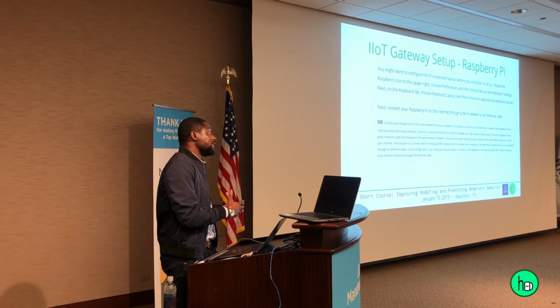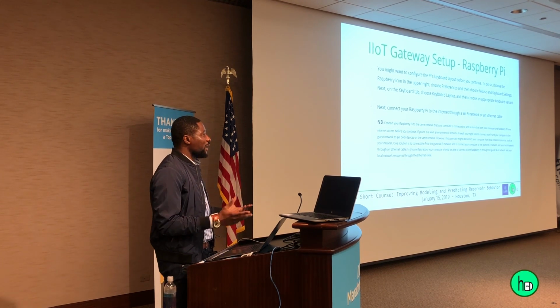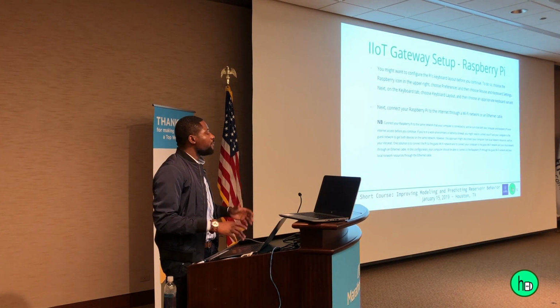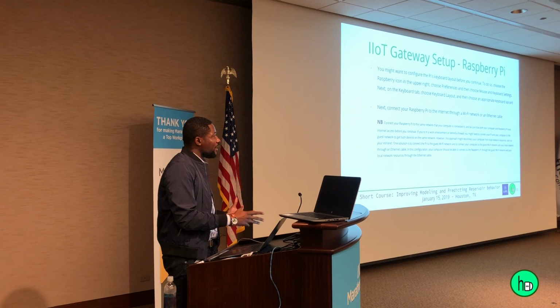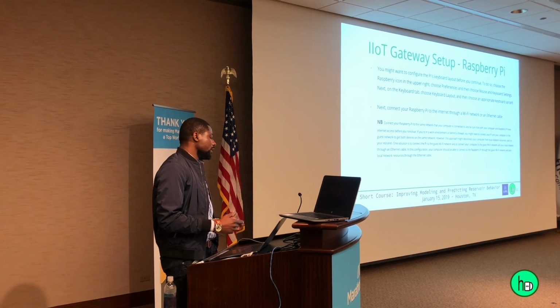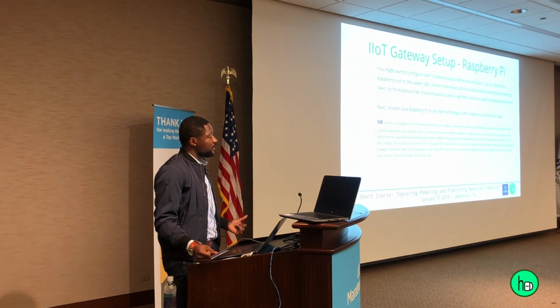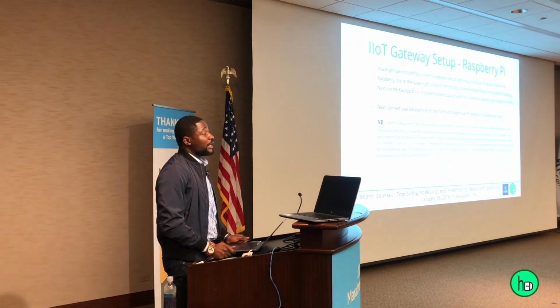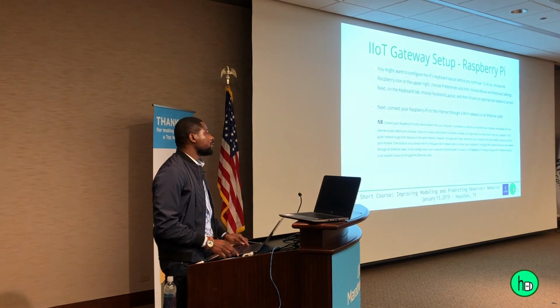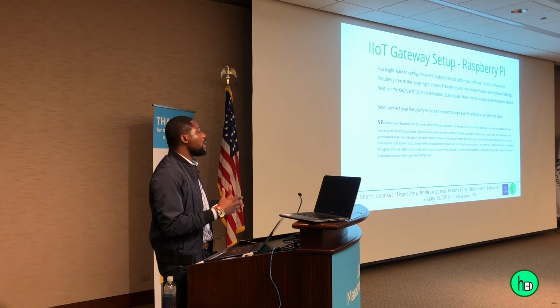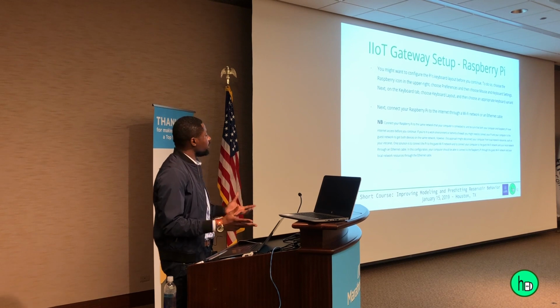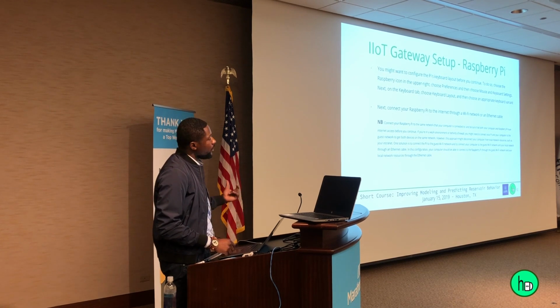So what I did this morning, if you heard me earlier, I said it was tough for me to set up my Raspberry Pi system. But eventually I was able to get my hotspot up, connect my laptop to it, then connect my Raspberry Pi to it. So your Raspberry Pi needs to be on the same network as the computer you'll be accessing it remotely from. You want to make sure they're all on the same network.